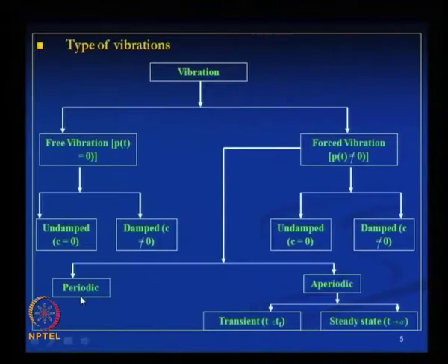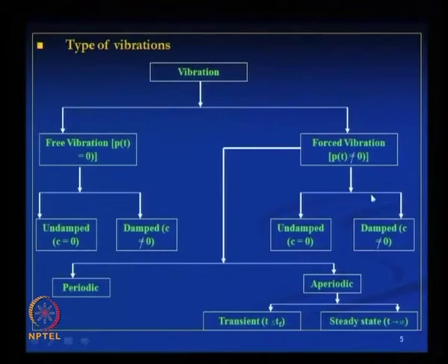Again, another way to classify the forced vibration, we have seen there can be two categories. One is called periodic forced vibration and another is called aperiodic forced vibration. We have seen the examples of periodic forced vibration, like any externally applied dynamic load, when it is applied, follows some period, meaning regular period, like any harmonic motion, in that case it can be classified as periodic type forced vibration, and aperiodic when it is not following any period, then we call that aperiodic forced vibration.